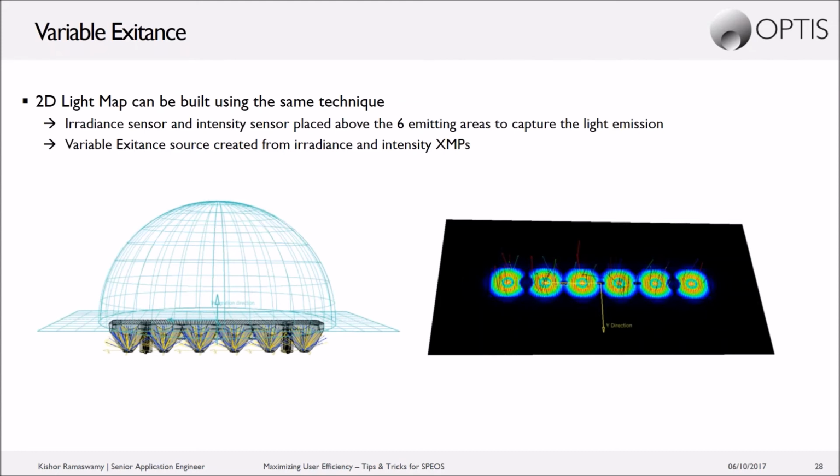From that, you can see the result that's created on the right, which has the 6 circles for each one of these collimation features, as well as the rays that are representing the intensity distribution. What this allows you to do is calculate all of this as a pre-simulation so that it doesn't need to be put into the actual longer-term simulation. You can just go based on this pre-calculated distribution, which saves time, especially if you're running many simulations on the same design.